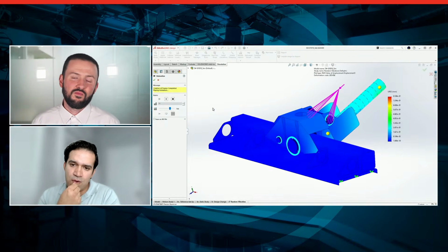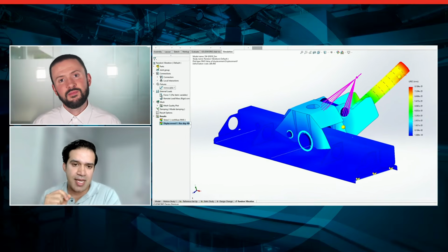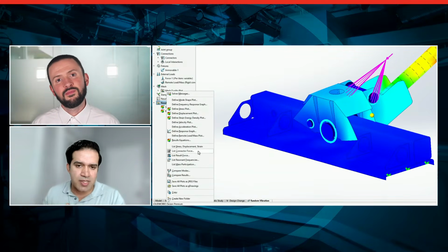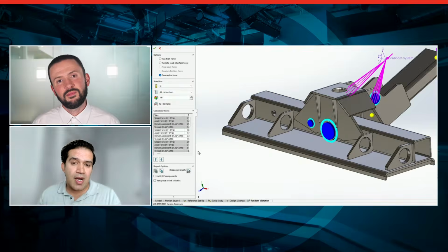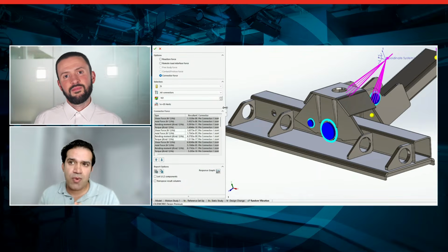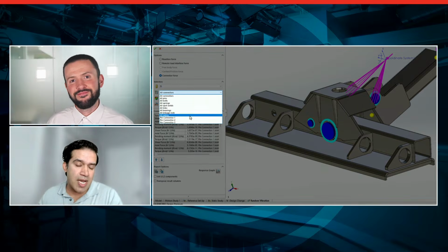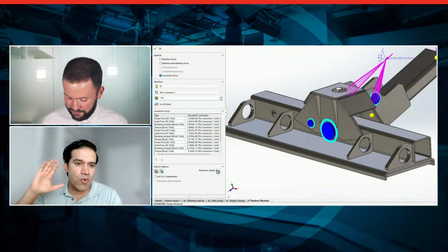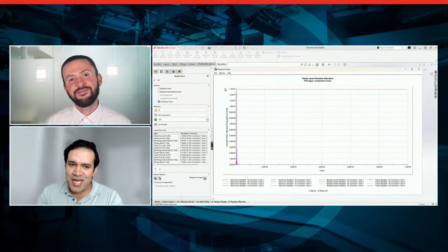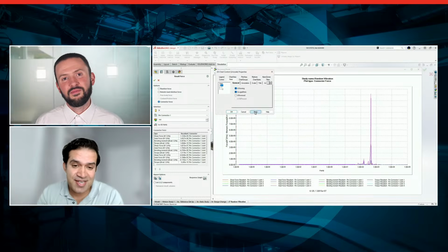And I think this video would be showing where the critical resonance is happening. So it gives you good insight on, okay, I'm running a random vibration on this, here's a critical response that needs to be studied a little bit more. And this type of insight is what's most important about simulation and what helps you make products that are going to last a lot longer and find some of these issues that might pop up that we won't know until later. So I would say a really good enhancement when it comes to random vibration is to be able to do these pin connectors now without having to have pins there.